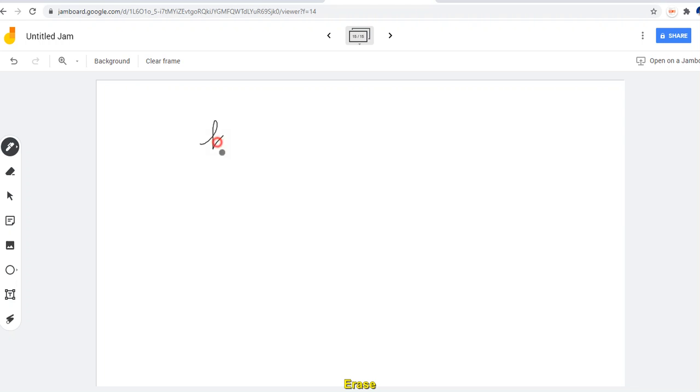So your K sub g, based again on the table, the formula that will convert your K sub y prime to K sub g, or it could be K sub y to K sub g. So you have options actually. So in this case, I'm just showing to you based on what is the original given. This is how we convert from K sub y prime, the given, to K sub g. So that K sub y prime will be divided by P times y sub Bm, and the rest will just be a matter of substitution.